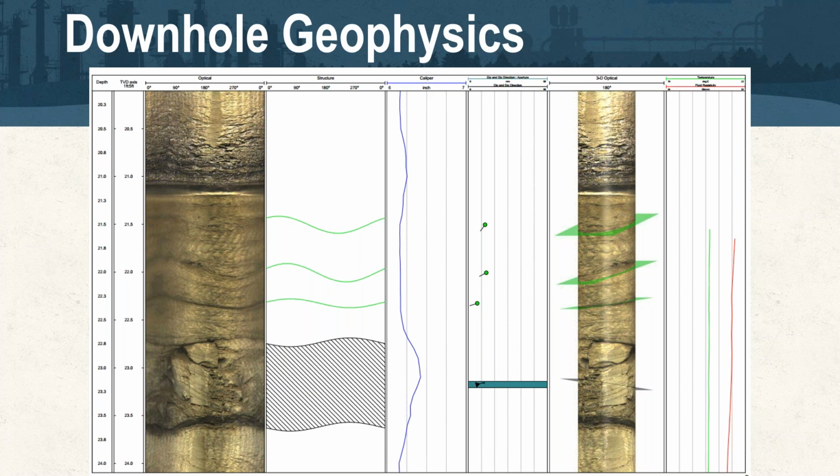So for safe measure and good best practice, we always recommend completing the core hole at an adjacent location, offset from your open boreholes, just for ensuring that you have the best possible chance of having a nominal caliper size for that specific borehole that you're going to be going back into later.